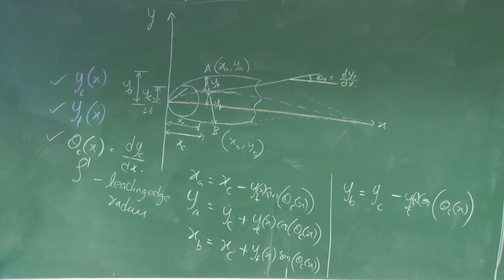In our previous lecture, we discussed how to plot an aerofoil given camber as a function of chord, the slope of this camber as a function of chord, and the corresponding thickness distribution about the mean camber line as a function of chord. And we also require the leading edge radius to complete this aerofoil.